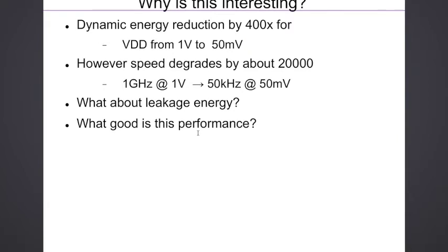And what that opens up is a lot of applications. Any microcontroller which you are using runs at a few megahertz, 8 megahertz, 10 megahertz, 16 megahertz. So for a lot of these applications, if you are able to run in the low megahertz, as far as the performance requirements of the application are satisfied, those now become open to this approach where you do very deep voltage scaling, where you scale down the voltage to these subthreshold levels.